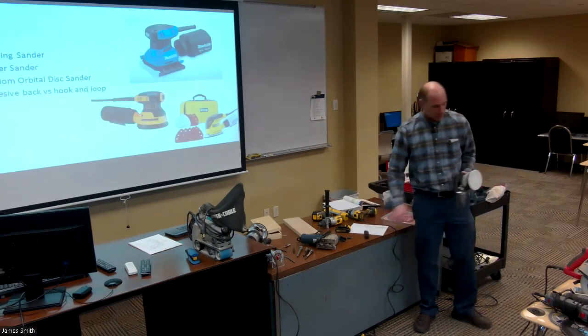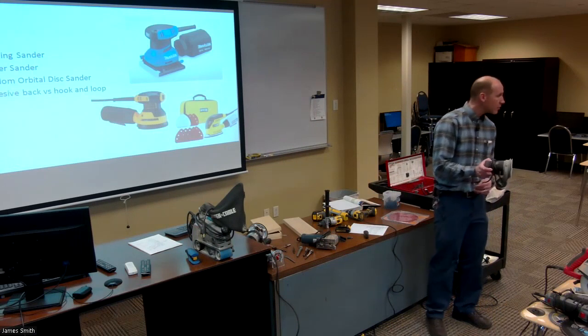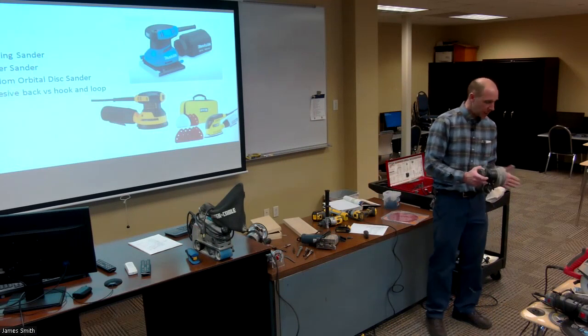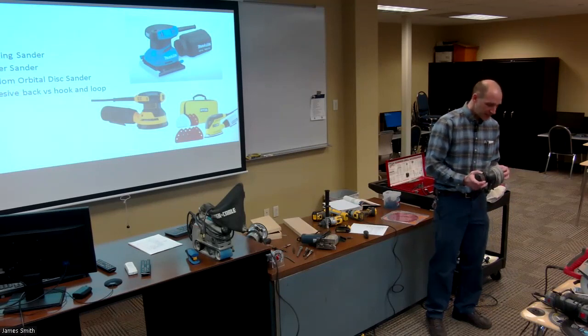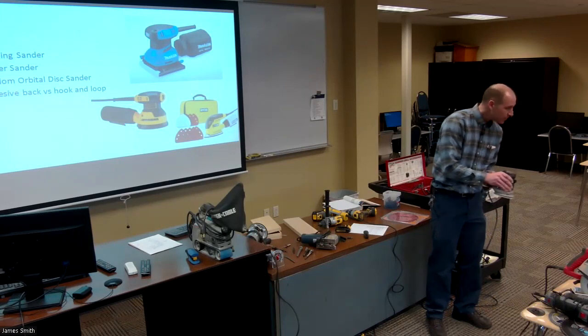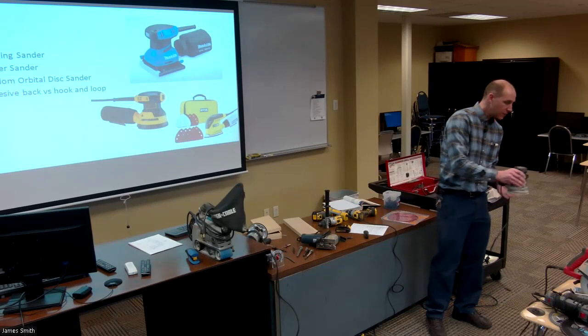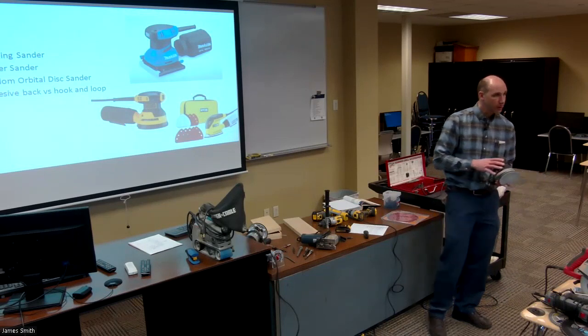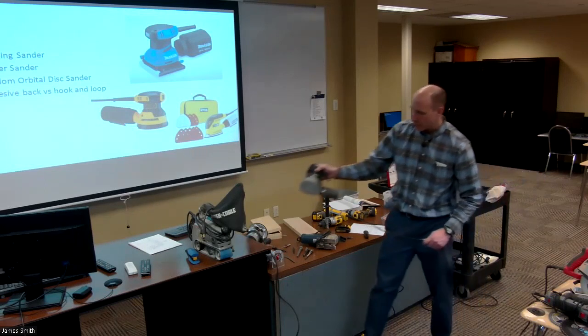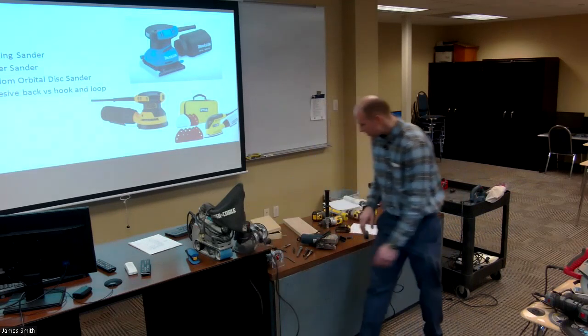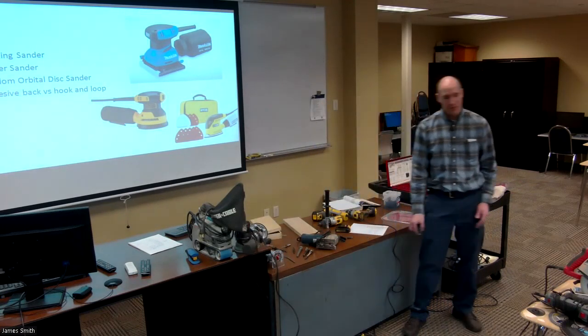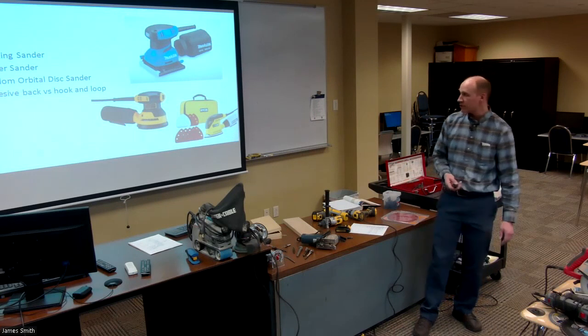Okay, for most of my sanding, I use these random orbital sanders, outfitted with a nice sharp 80 grit sanding disc. You can remove a lot of material really good, really fast. Just keep that tipped up on edge, so you're using kind of this one side, and you can use a systematic approach. You can do a very good job and sand relatively large surfaces very flat and smooth, and it's used a lot for finish preparation that way.